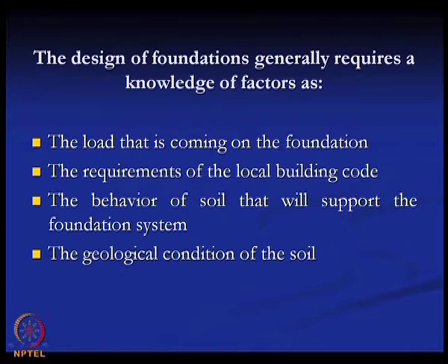Now, first we start with the fact that the design of foundations generally requires knowledge of factors such as the load coming on the foundation, the requirements of the local building codes, the behavior of soil that will support the foundation system, and the geological condition of the soil. These things are very important when you design a foundation. We should know how much load is coming on the foundation, then what the required design codes and building codes of the area are, and the behavior of soil that will support the foundation system, that is, the soil properties. We should know the soil properties before we start the foundation design.